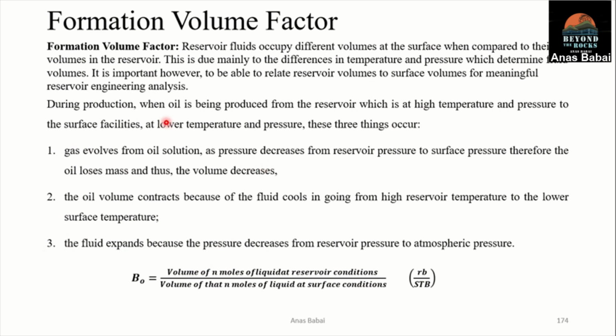Before that, we have the definition of the formation volume factor. In a simple way to explain it, we need this factor because the amount of hydrocarbon, or the volume of oil and gas in the reservoir, is not the same as its volume in the surface condition, because in the reservoir it's subjected to high pressure and high temperature, which is going to cause certain changes.